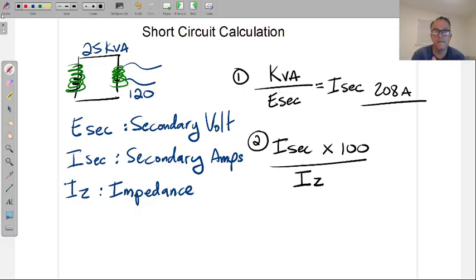For a home, 4160 to 240 on average, or maybe 12,000, all depends. Somewhere around 2.5% energy loss, 3.5% energy loss, depending on the manufacturer of the transformer. Again, this is a transformer manufacturer problem, but all we need to know is what is that number so that I can do this calculation. So let's throw one in here. All right, let's say it is 3.5.